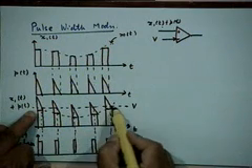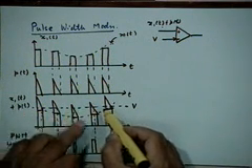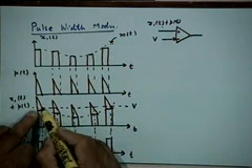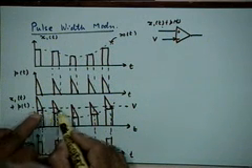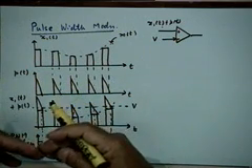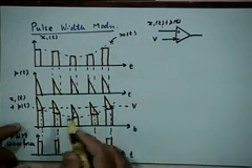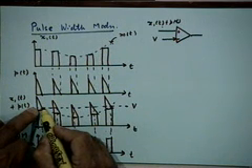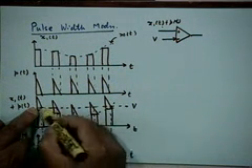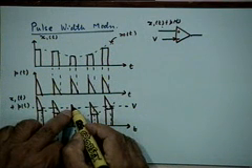The point of intersection of this constant voltage line with this added waveform would generate different durations during which the sum amplitude is larger than the threshold. Here it is larger than the value V for a much larger time than here, and so on and so forth.